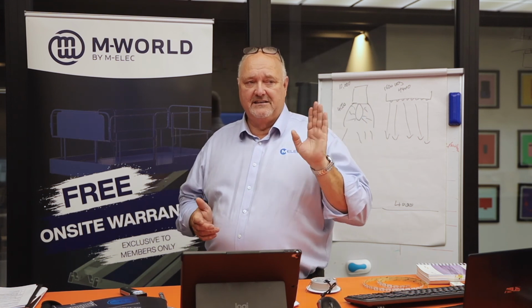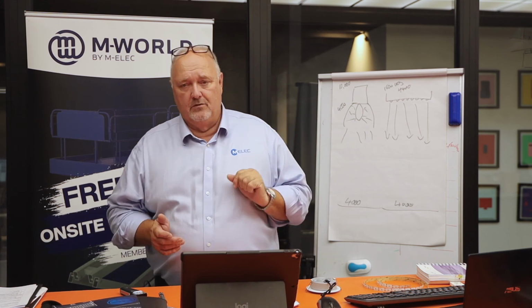A ballast is not a power supply at all. Once the arc is done, the ballast quickly reduces the voltage and regulates the electric current to produce a steady light output out of a fluoro. When you see a fluoro start to flicker, you know it's either the ballast or the starter that's starting to let go, or the tubes have let go. So a ballast is something that's totally different.